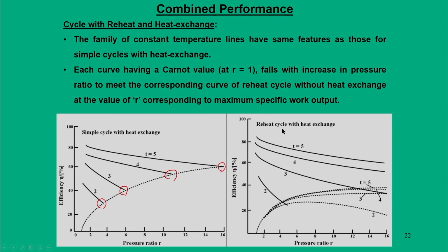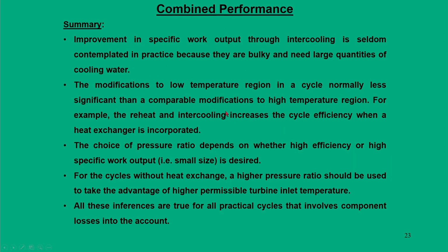Side by side with reheat and heat extraction cycles, what we can say is that with a very high temperature reheat cycle we can achieve a large pressure ratio. So, this is the very basic philosophy. Of course, this circuit becomes too complicated, but just to show that such a cycle is also thermodynamically possible.